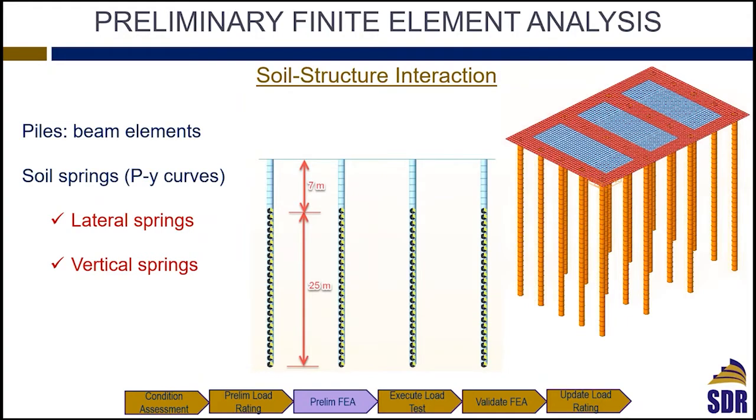And actually, MIDAS has a built-in function for the integral piers and the monopiles or the pile and the column, where they can represent the soil using lateral springs and vertical springs using the P-Y curves method. And I think the lateral springs are nonlinear springs and the vertical springs are linear springs. So this way you also account for the flexibility inherent in the system when you account for your foundation.